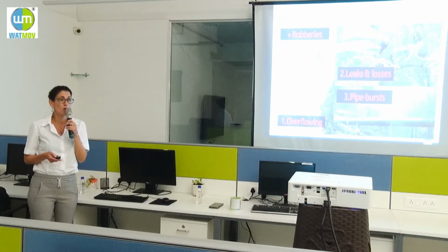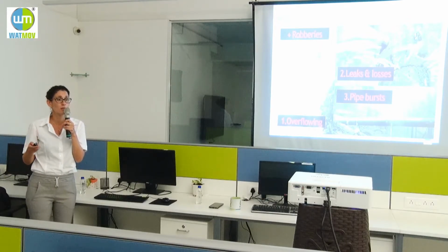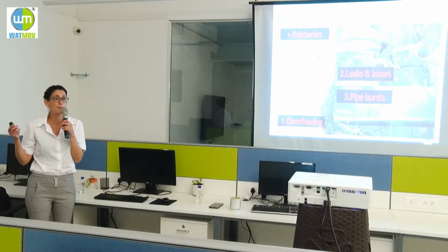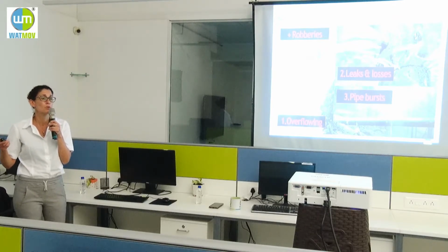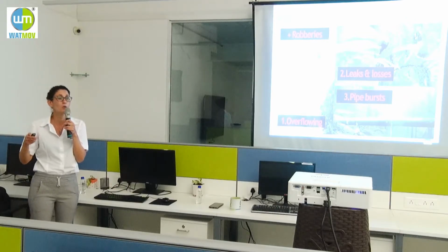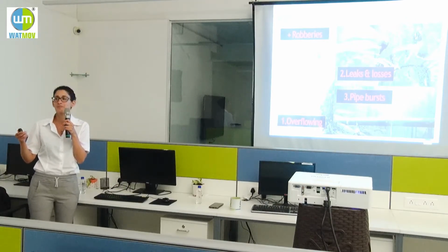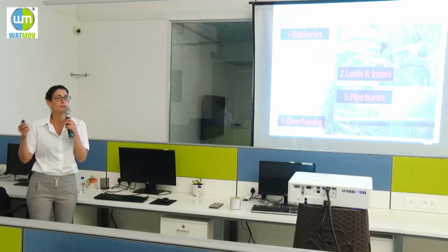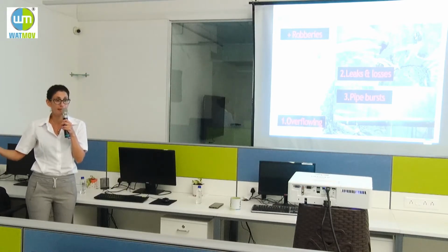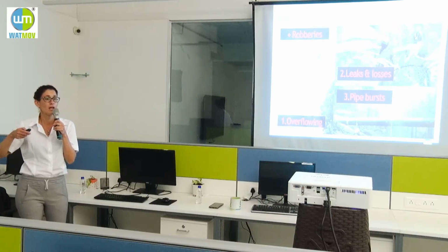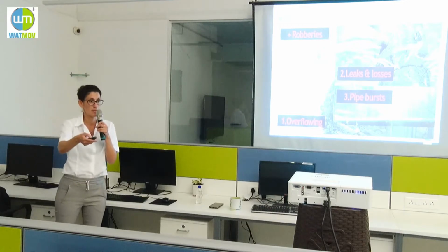It can also increase the risk of pipeline burst, okay? When we have excessive pressure all the time, you can find on Google all kinds of research that connected the pressure at night in the DMA to the chance of bursts in these systems.